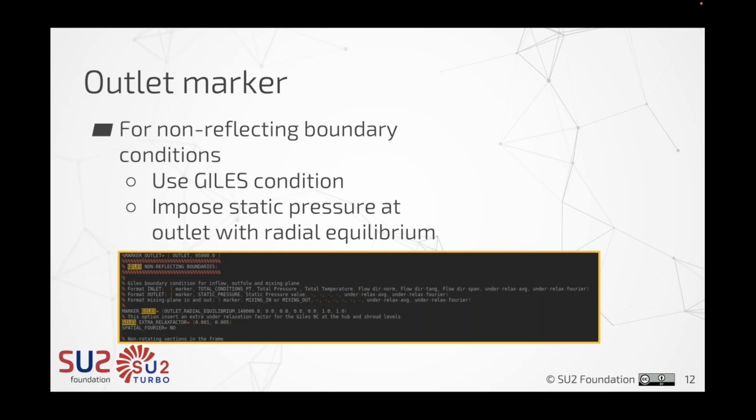So I was predisposed to a slight prejudice because I wanted both to be somewhat similar. So I had to play with this factor. So basically the factor, there's one column for under relaxation, and the other column is the degree of percentage you want to apply it over the radial distance from the hub and the radial distance from the shroud.